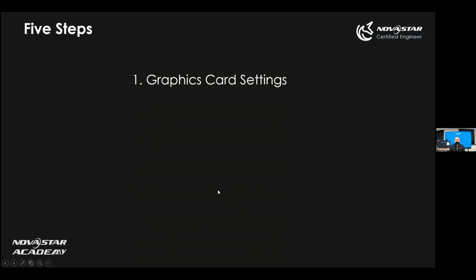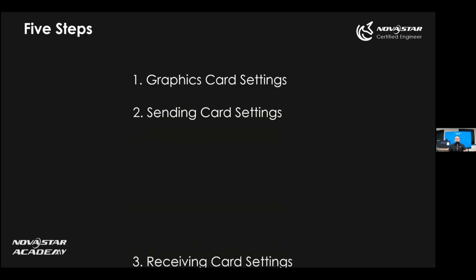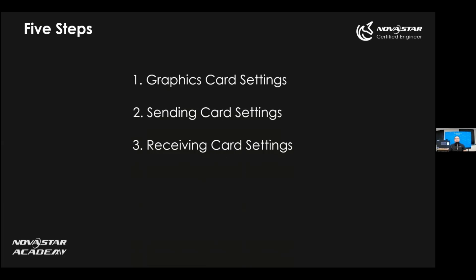The first step is the graphic card settings. I believe the people who said 4 steps didn't include this one. Yes, this is important, and later I will show you why. The second step is the sending card or sending controller settings. The third is the receiving card settings. The fourth is the screen connection.